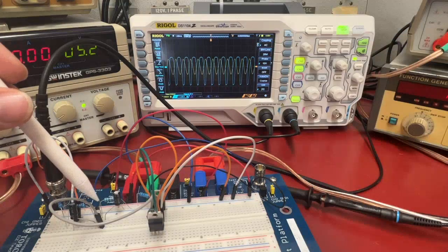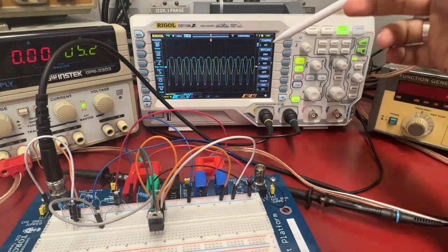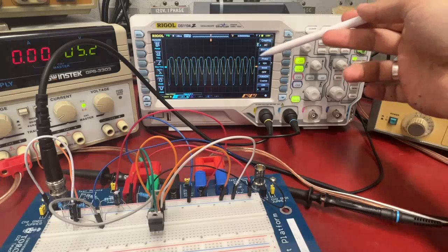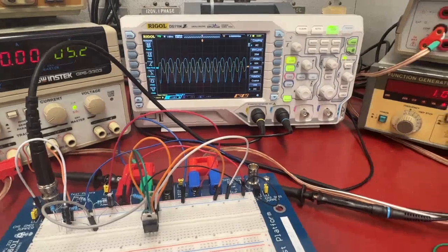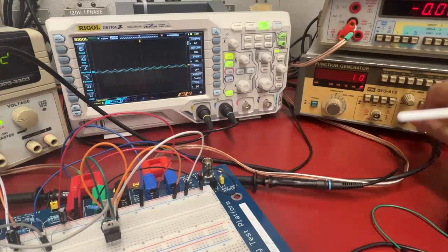After adding the bypass capacitor to the emitter of the amplifier and measuring the output at the collector, you may notice a significant distortion as a result of the high gain of this amplifier. So you need to reduce the input amplitude to avoid this condition.